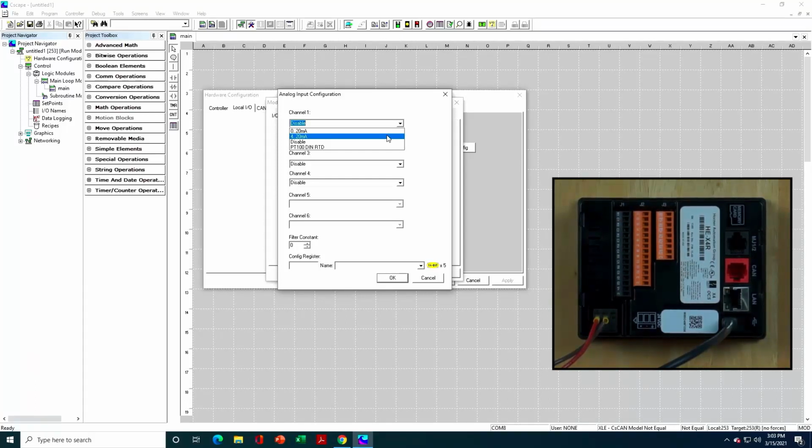Now, if you do have a value below 4 milliamps coming in, let's say because your sensor, for whatever reason, is disconnected or reading quite low, you will still get a negative reading that will tell you that you've got an issue on that sensor. Either it's low or it's disconnected. So almost always, for the best resolution, 4 to 20 milliamps is the better choice.